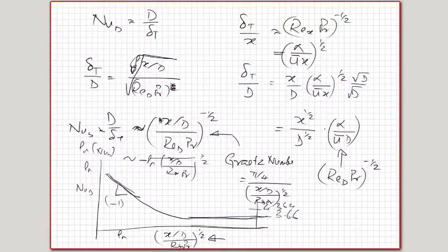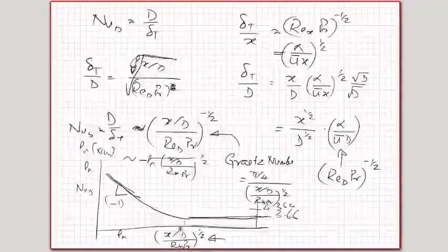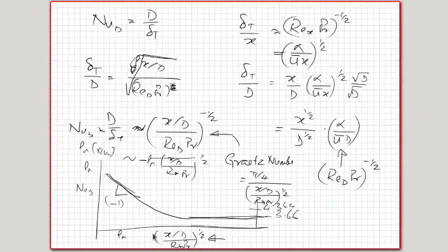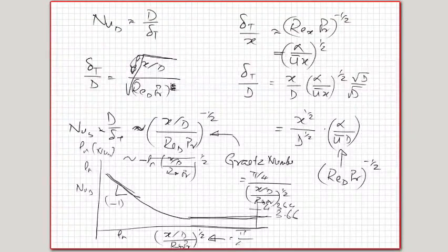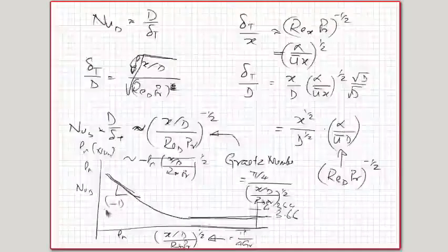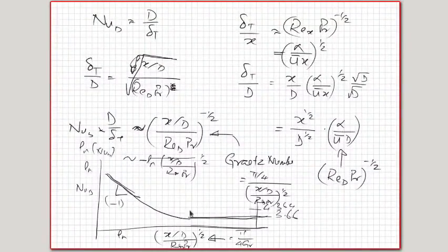So basically this multiplied by pi by 4 will be the Graetz number. So in the x-axis, actually, it is pi by 4 Graetz number. This is what the x-axis is usually in the log scale, and this is how usually the plots are. This number has significance because of the way the Nusselt number varies.